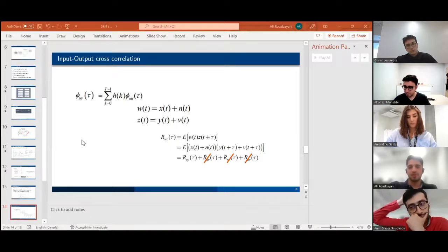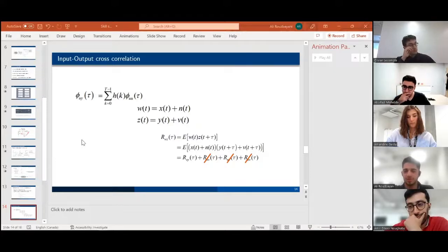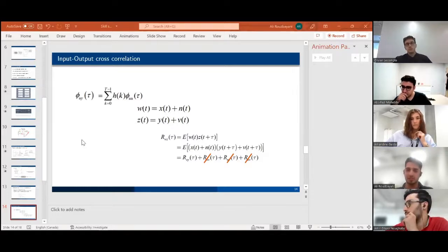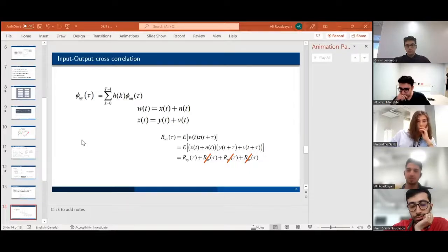When we try to derive the frequency response, identify the frequency response function, the ideal thing to do is to give the system a white noise, a white input. Just as I said that if we want to do an IRF, we have to give the system the impulse, in the frequency domain we should give it the white noise, the white input, because it contains all these sinusoidals. It will be the best identification.